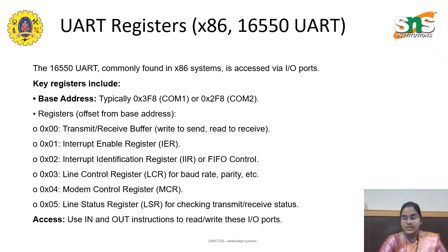In this lecture series, we will discuss the UART registers and UART's architecture. UART stands for Universal Asynchronous Receiver Transmitter. For an asynchronous system, we don't have a clock signal, so we have to use the start bit and stop bit. Here we are using the 16550 UART, commonly found in 8086 systems, and this is accessed via the input-output pins.